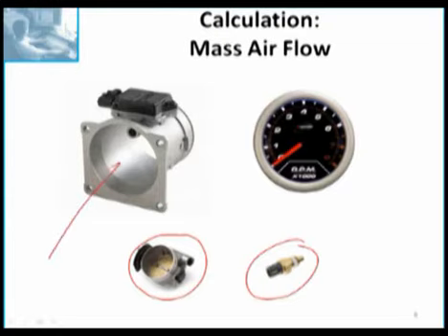Another thing about the mass airflow sensor is that it really doesn't measure all the air coming into the engine. It actually measures a sample of the air. That sample can get a skewed reading by some debris which happens to be lodged on the air filter or on the screen in front of the sensor and disrupts the airflow. Another item that can disrupt the airflow into the sensor is a malformed air filter that has a cone that's the wrong size. So again, if the mass airflow sensor is out of range or dirty, you basically end up with lean DTCs. Remember, on this system, a vacuum leak is lean all the time, always going to be lean. A duct air leak could be lean at idle and under load.